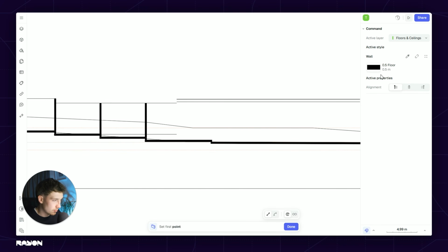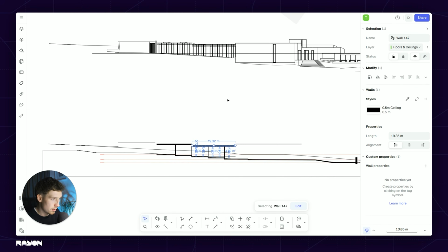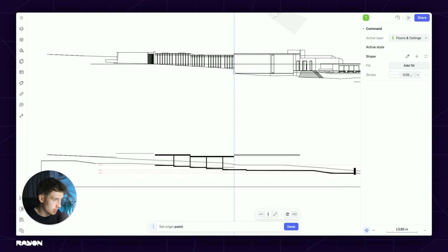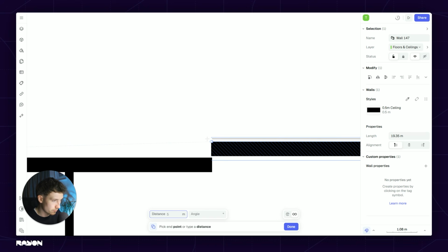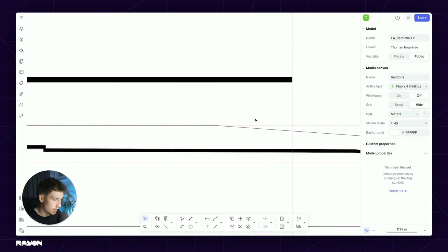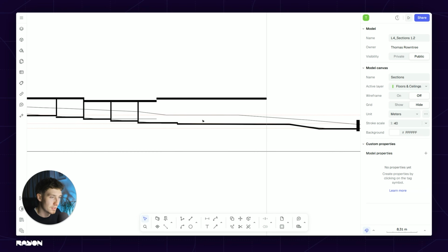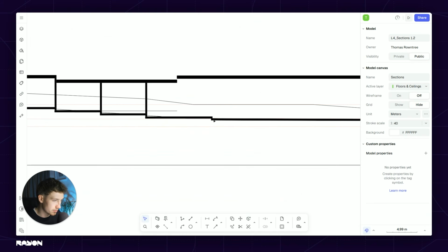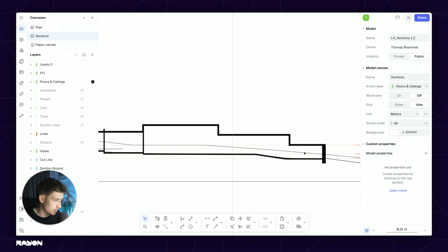Now I'm just going to spend a bit of time drawing in some of the ceilings. That will follow along there. That will follow along there. And if we use once again our grid lines, we can then see that it almost steps up at that point. So we're then going to copy that up. So we have a very generous, if we just dimension that, very generous 6.5 meter floor to ceiling height space for the gallery, which is a really great space. And it will step down here at this other end to this lower cafe level.